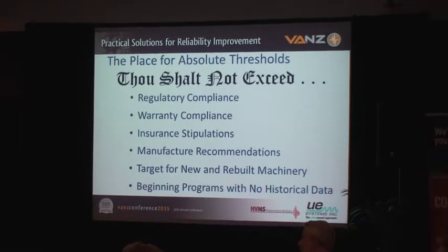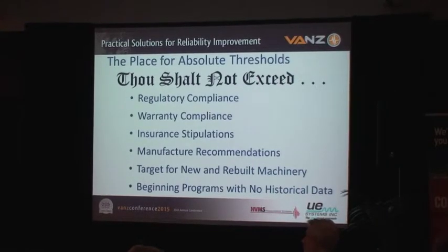There are recommended amplitudes that you can use. You can follow the ISO guidelines. Technical Associates, I know there's a number of folks that are a big fan of the proven method that Technical Associates recommends, and they've got bandwidths and amplitude thresholds. For folks that are new to condition monitoring and evaluation, at least from a vibration perspective, I think the proven method gives you a really, really good starting point.